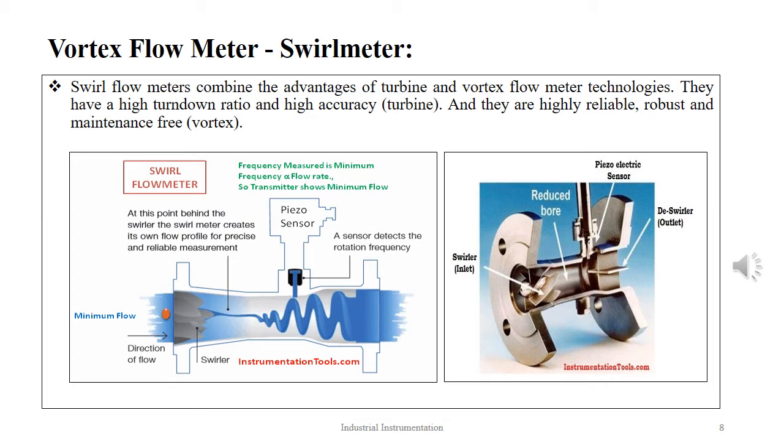In the area where expansion occurs, the swirling flow precesses or oscillates at a frequency proportional to the fluid flow rate. This precession causes variations in temperature sensed by thermistors. The amount of heat extracted is a function of the fluid velocity.